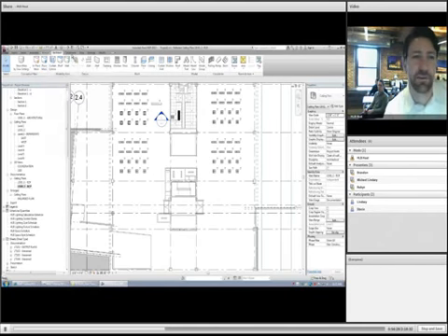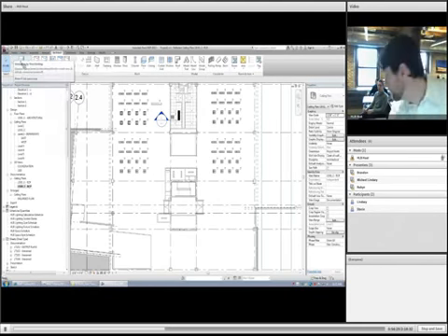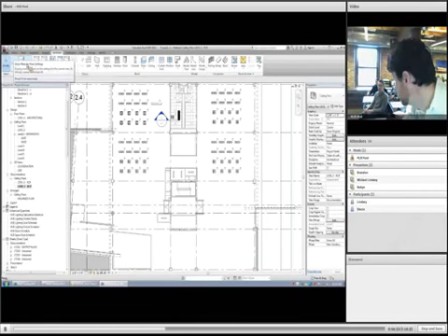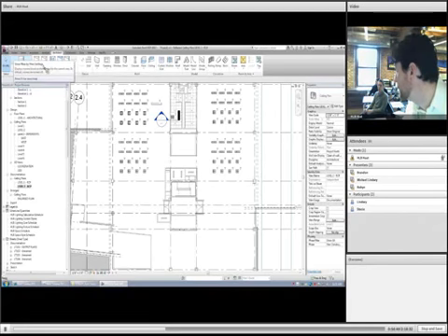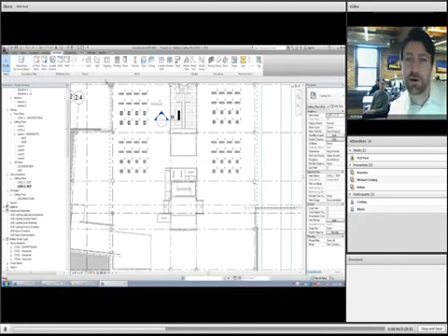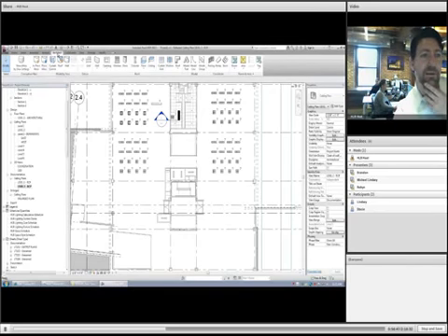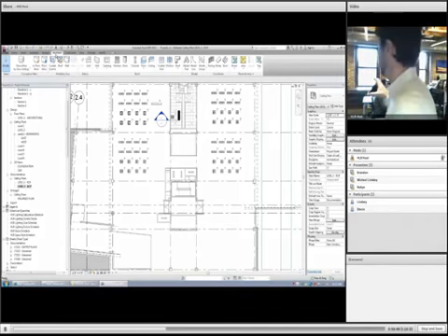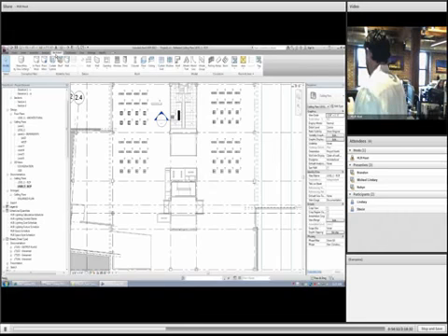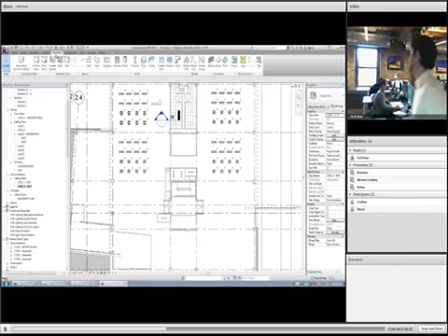There's a setting in here. What's this? You can tag all ceilings, can't you? Like the ceiling heights, or do you have to go through? But will it recognize ceilings? I think you'll have to do it individually. It will. But the thing is, let me get back to you on where this is, but it basically comes down to the spot elevation tag knowing whether or not to reference the level that's closest to it, or the one that goes all the way down. And there is a place to change that.